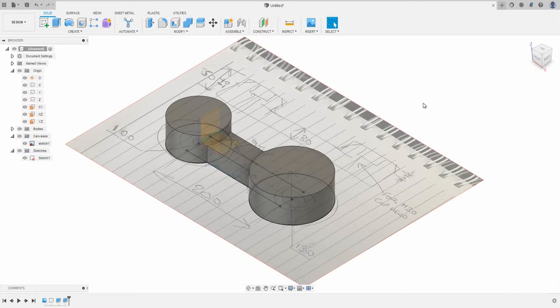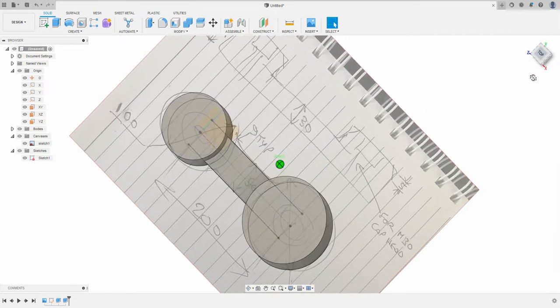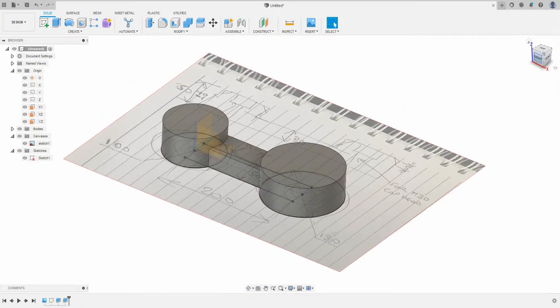Okay. Now you'll notice there's all sorts of things on this drawing that I haven't done yet. So there's a 9mm fillet radius, there's a chamfer at the top of the 2 pillars. We can add these later. Don't worry about anything with chamfers and fillets. We do this afterwards. Get the solid model created first and then worry about these later. Don't put them into the sketch. You don't need to. I know you can fillet in the sketch, but most of the time this sort of thing can be added afterwards.